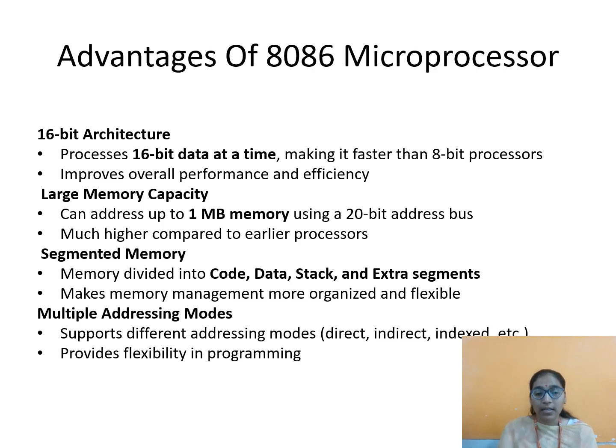Large memory capacity: it can address up to 1 MB of memory using a 20-bit address bus, much higher compared to early processors. Segmented memory: memory is divided into code segment, data segment, stack segment, and extra segment memory, which makes memory arrangement easier, more organized and flexible. Multiple addressing modes: it supports different addressing modes, direct, indirect, indexed, etc., which provides flexibility in programming.